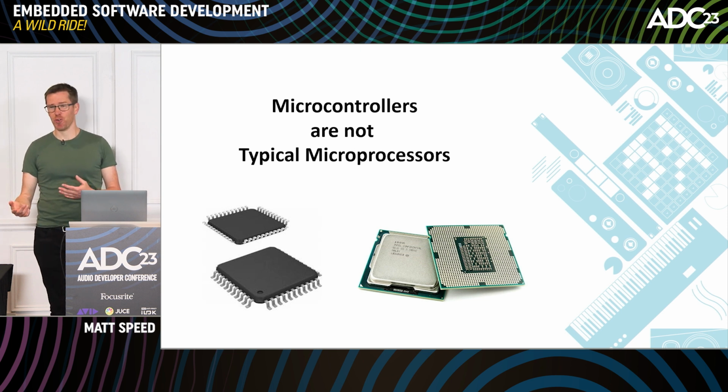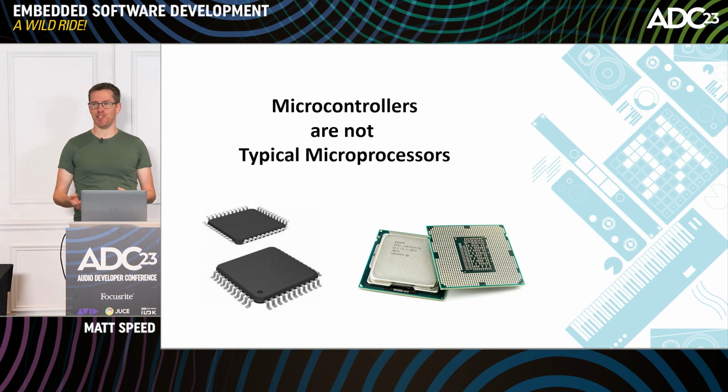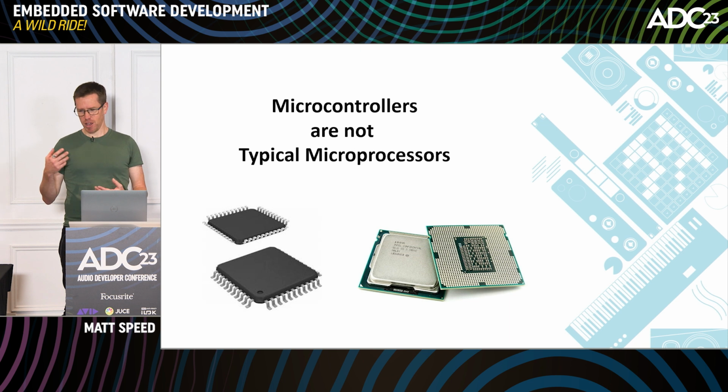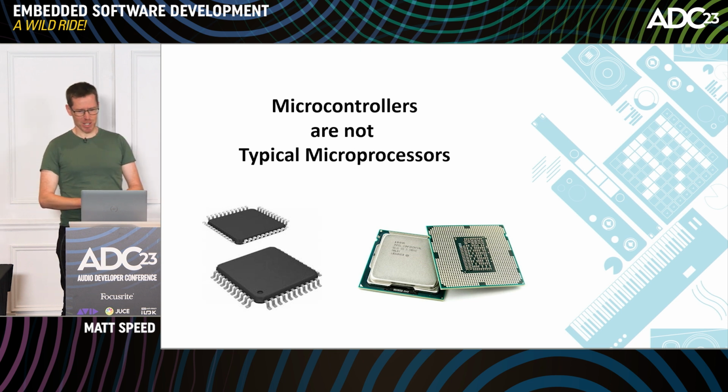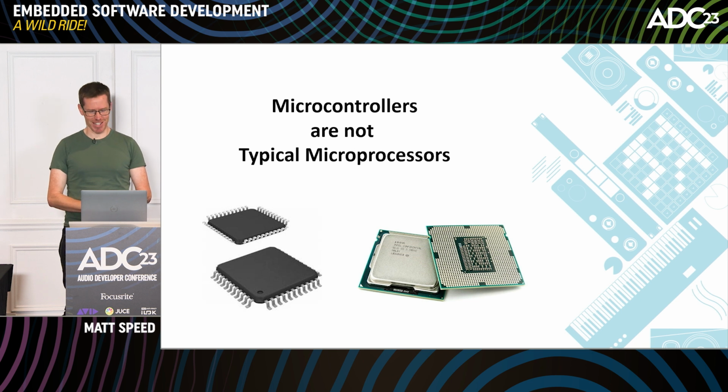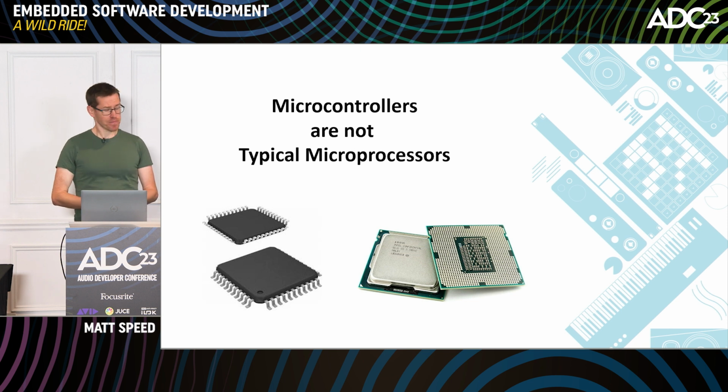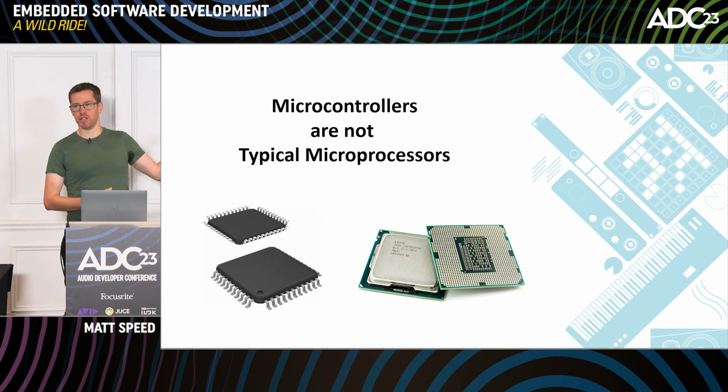Microcontrollers are a lot more straightforward. You're not going to get fancy features like multi-issue or out-of-order execution or branch prediction, which is a bit of a mixed blessing because it means a Novation Circuit's never going to be vulnerable to a Spectre or Meltdown side channel attack. But yeah, they're not quite as clever and a bit more simple. All the memory it needs can be considered like L1 memory, and it's right there on the chip.